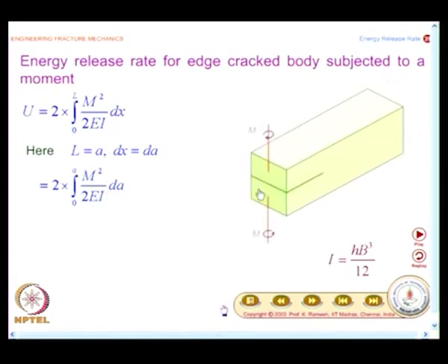You should recognize the plane of bending and then write the moment of inertia, and look at how it bends and how the dimensions h and b are shown. When you look at that, you get I as h b cubed by 12, and just substitute it in; it is a fairly simple exercise.